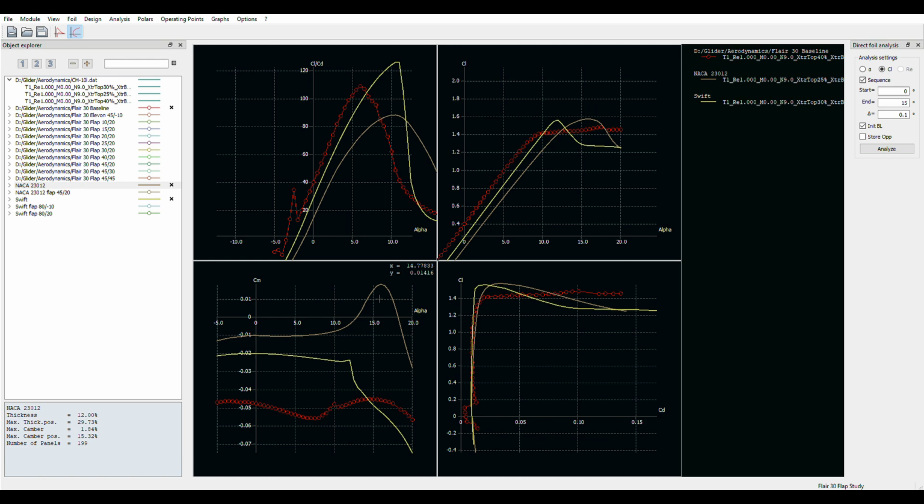The increment of more elevon I have to put in to get an incremental change in the L over D is smaller than these other airfoils. It's easy to trim at a high angle of attack, and it's easy to avoid a full-on stall.